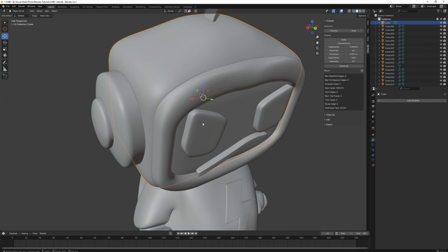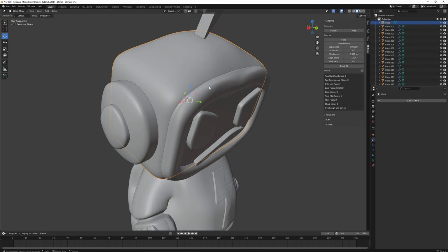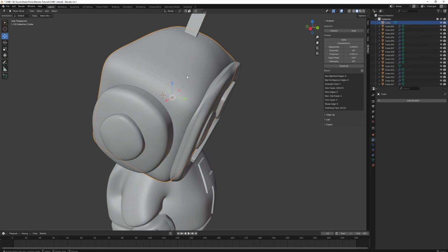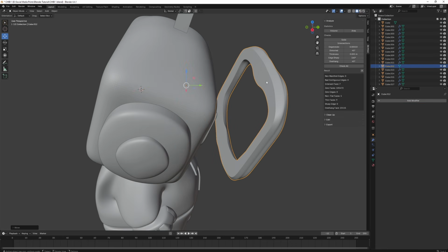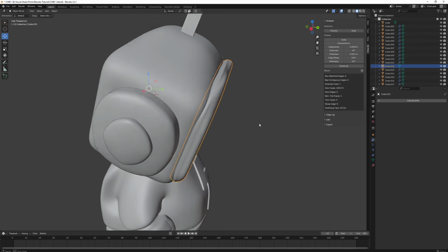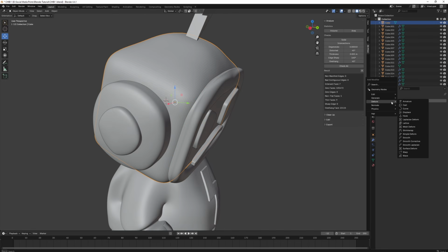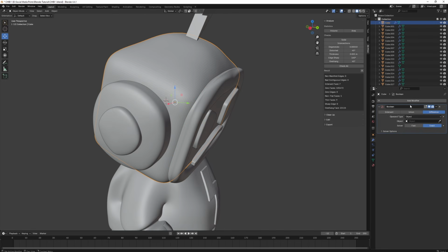Now while you could just export this thing as an STL right now, it is a nasty model to print in one piece. This is another reason why I separate everything. We can print each individual object separately, and when printing things it is best to have one side that is completely flat so it has a nice base for the first layer and we can reduce the need for supports. We also need to make sure that each part can fit into each other part. We're going to be snap fitting these together or gluing.